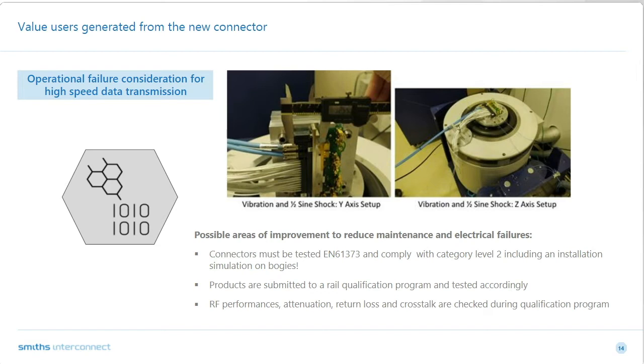So in some ways, what we were trying to do is that we were not only taking care of the customer's overall use cases, but we were translating those use cases to different failure modes and the effect that might have through the connector to their overall cause, and designing something that ultimately helps to deliver a robust design with reliable connectivity.